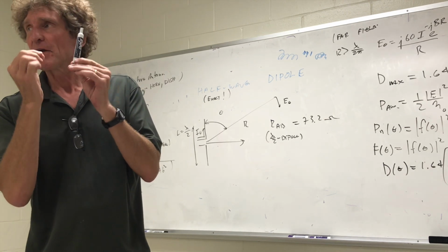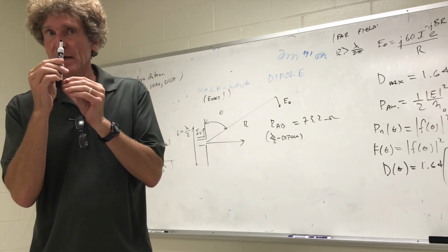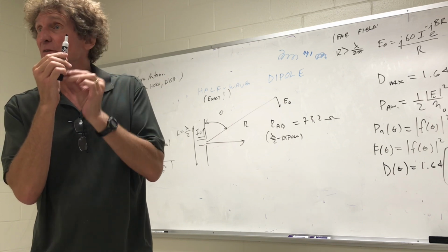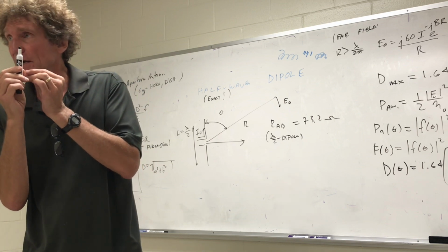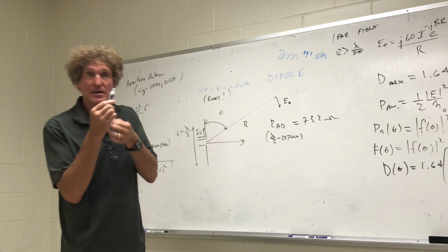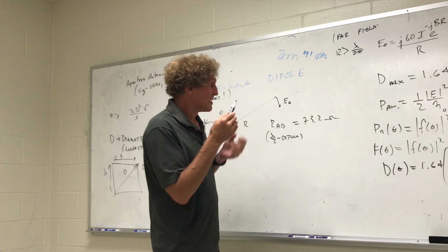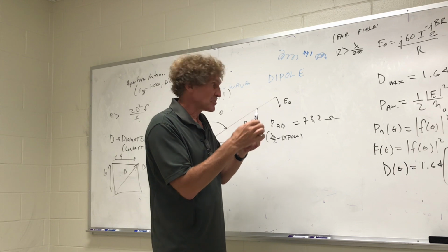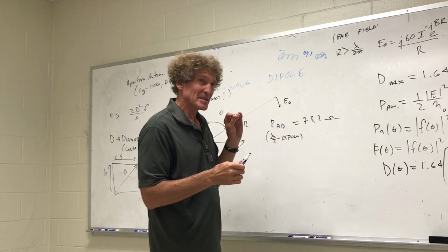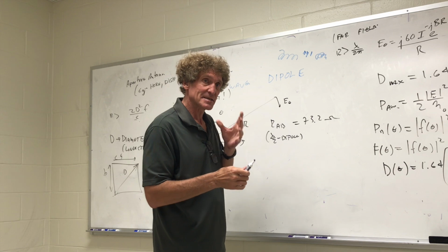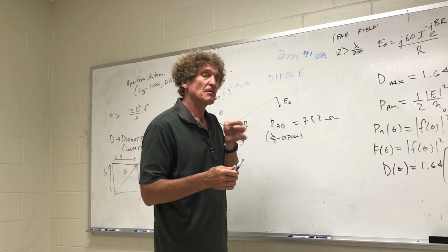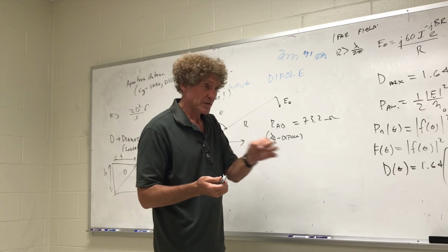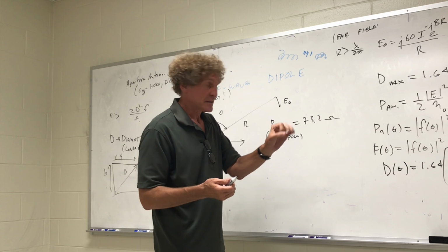When you get very, very thin antennas, you get a problem with losses. R loss goes up. You basically have a resistor in there because the copper will heat up. It doesn't have enough cross-sectional area to lower the resistance. And as you make the radius larger and larger, this starts going down, as I understand, to about 72 ohms. So just realize this is an approximation that's accepted. It's for a very thin wire, and we're not driving a lot of current. As you drive more and more, the wire gets fatter, and this will go down.